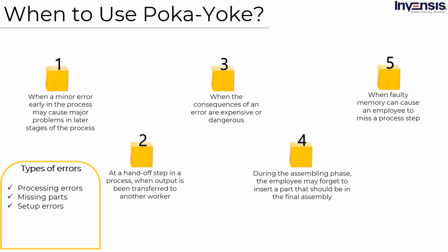Setting machine adjustments wrongly or using the wrong tooling to set up the machine: setup errors. Errors that happen in production when a wrong measurement causes a machine breakdown or stoppage of production: production error. Failing to use the right parts in a process: improper parts/items. Taking measurements wrongly in a process, machine adjustment, or the dimensions of a part coming from a supplier: measurement error. Performing an operation incorrectly or having the incorrect version of the standard operating procedure: operations errors.